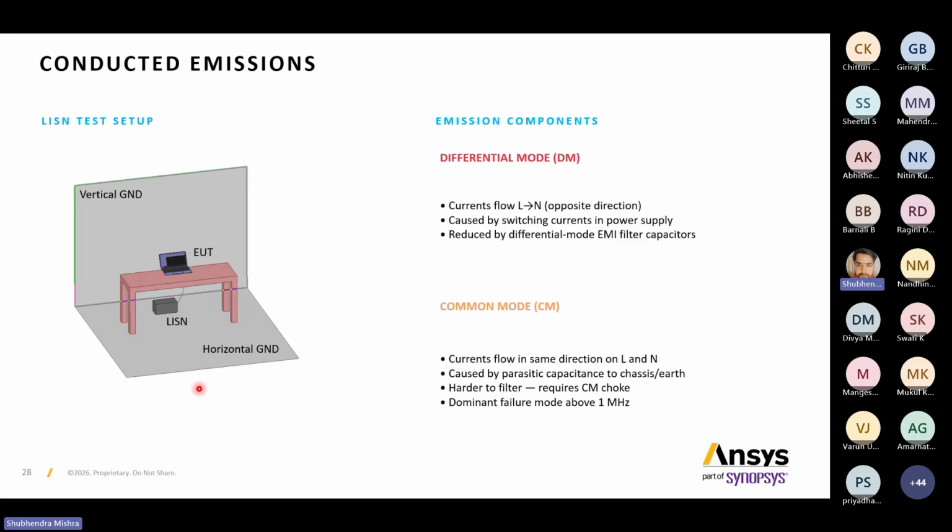Next one is conducted emission. Here you can see this is basically our test setup. In this, there are two modes, differential mode and common mode. In the differential mode, current flows in opposite directions. When I talk about the common mode, current flows in the same direction. You are already engineers, so these things are much clearer.